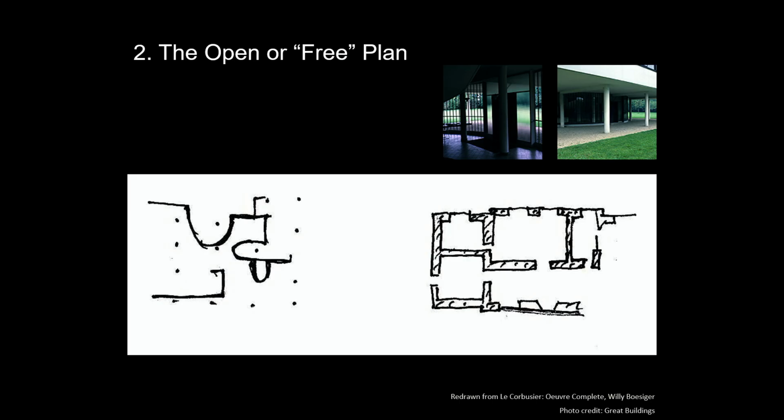Le Corbusier describes point 2 as follows. The free designing of the ground floor plan. The support system carries the intermediate ceilings and rises up to the roof. The interior walls may be placed wherever required, each floor being entirely independent of the rest. There are no longer any supporting walls, but only membranes of any thickness required. The result of this is absolute freedom in designing the ground floor plan. That is to say, the free utilization of available means, which makes it easy to offset the rather high cost of reinforced concrete construction.